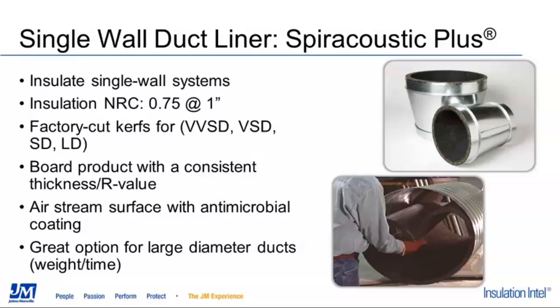If not done correctly, the insulation system could experience compression due to the settling of the inner metal perforated core on the lower insulation, which of course could lead to loss of R value, reduction of NRC, and ultimately could result in condensation buildup on the outer wall of the system, which all of these are not good.